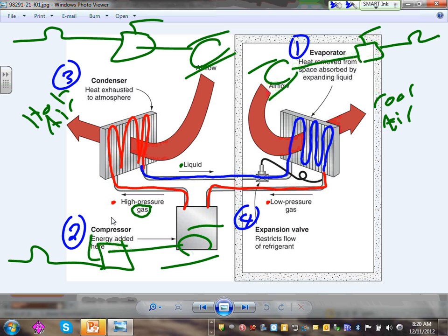Any comments, any questions about this? Does it make sense? Now, my job and yours, Darren, is not to put the system together. If you understand it, you'll be better as a designer. My job is to come to the mechanical guy and say, where is your evaporator blower? This is your evaporator blower. I need to wire it. So you provide an overcurrent protection device, a disconnect for the evaporator blower.